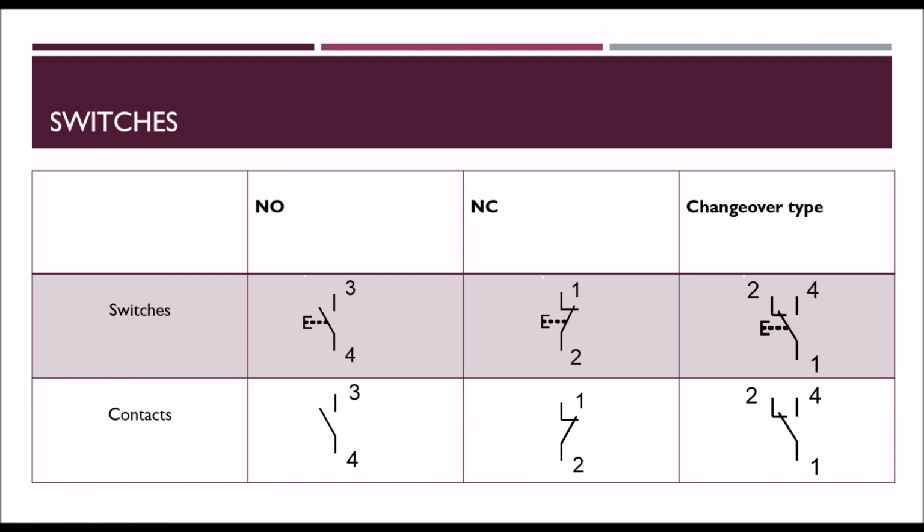Numbers are very important, especially when you are doing the wiring. Say, for example, you are a design engineer and you have designed the circuit, but when you give it to the operator level, without numbering it's very difficult to wire it. The operator will have difficulty in actually doing the wiring. So numbers are important so that the operator will follow the numbers.